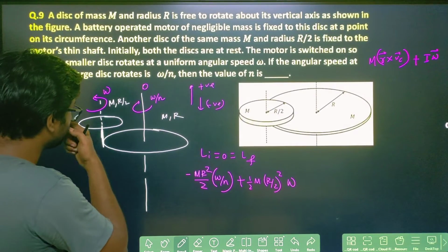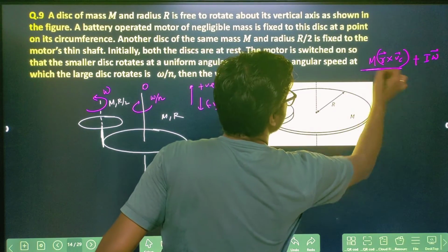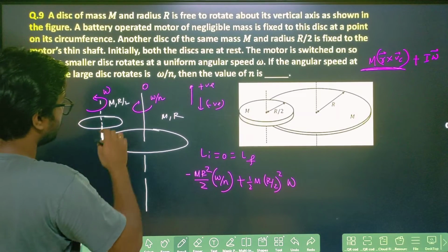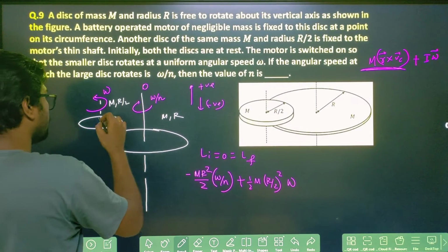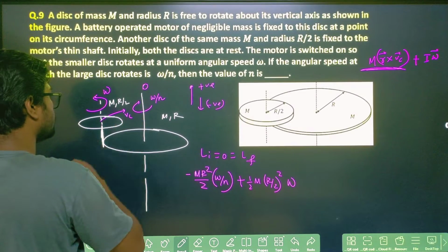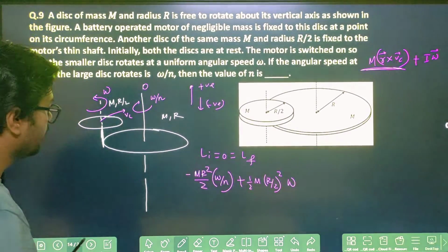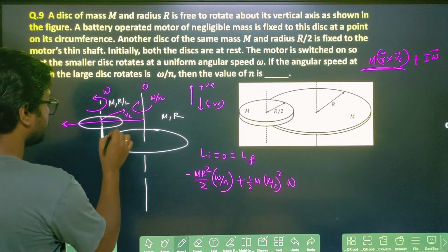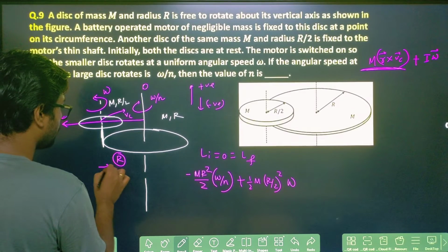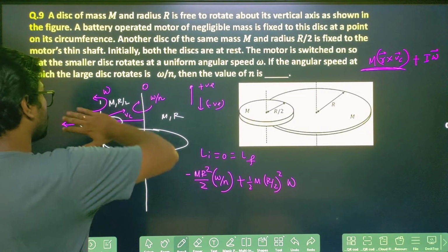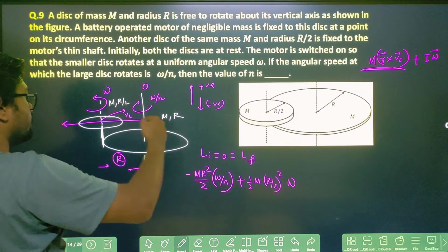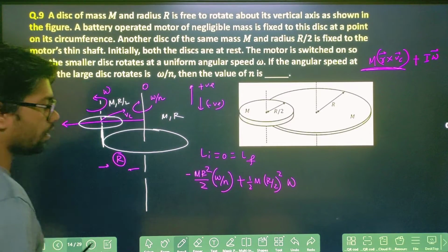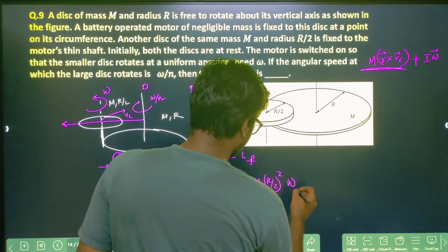Now for this term, if I want to write, obviously it is rotating like this, bigger disc, so it will move also along this direction. This is your Vc, right? It will move along this direction. And R will be from here to here, this distance, capital R. So R cross Vc is also downward, right? You see here R and Vc are into the plane. So R cross Vc is again downward, so you have to write down again the minus sign.